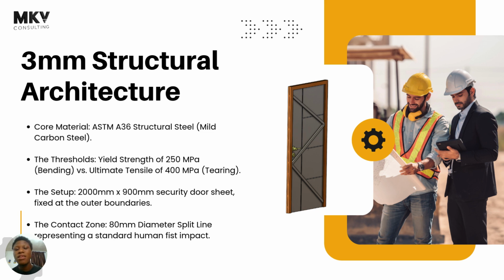ASTM stands for the American Society for Testing and Materials, an international standard. Those details are not important, just the international standard. Then the A tells you that this material is a ferrous material. The 36 at the back is the most important part, it tells you the yield strength: 36 kilopounds per square inch, or approximately 250 megapascals. So now we know our material.